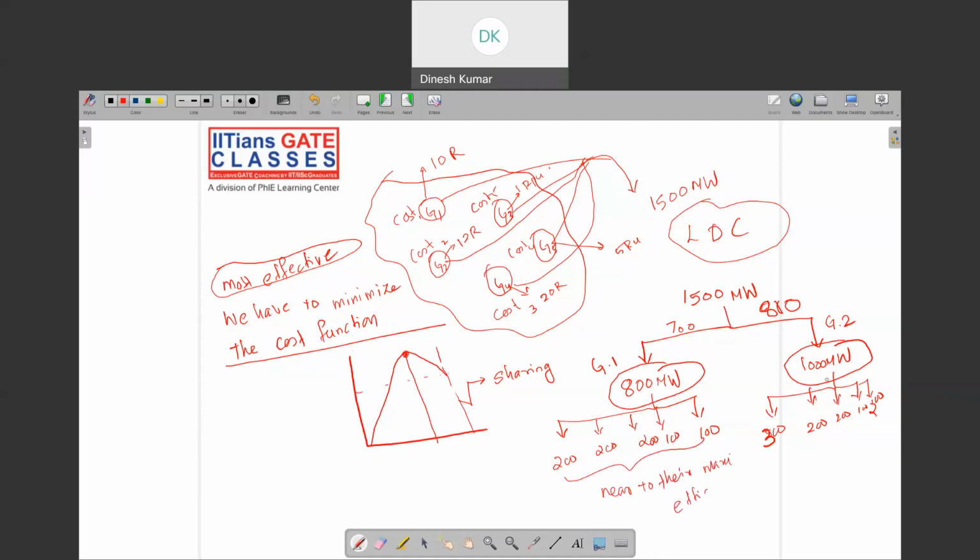So similarly, here this 800 will be distributed between these 5. So what is the way? Okay. In earlier times, when there was no computer, all this kind of algorithm was not there. So what they would do is choose the one having the maximum efficiency, right? The efficiency of this is like 85, 83, 82. So they would first load this to full, then load the next efficient one, then the next efficient one, then the next efficient. So we will get 700, and they would stop there.